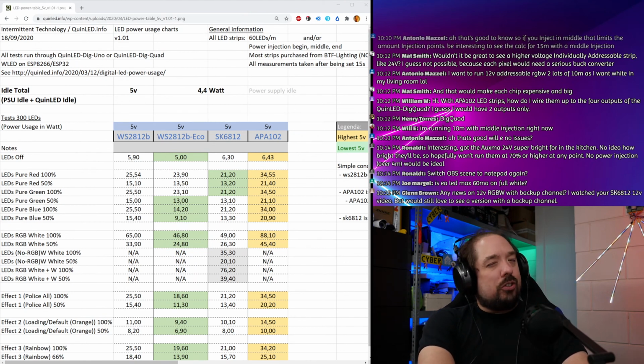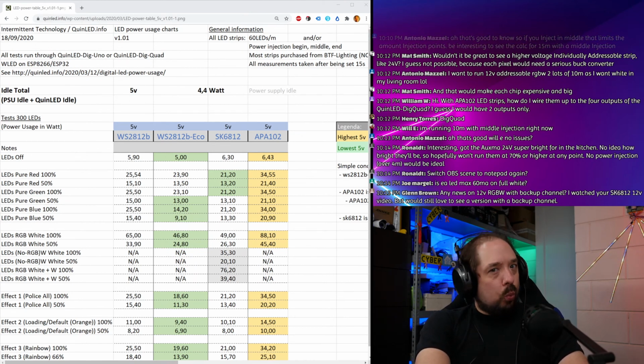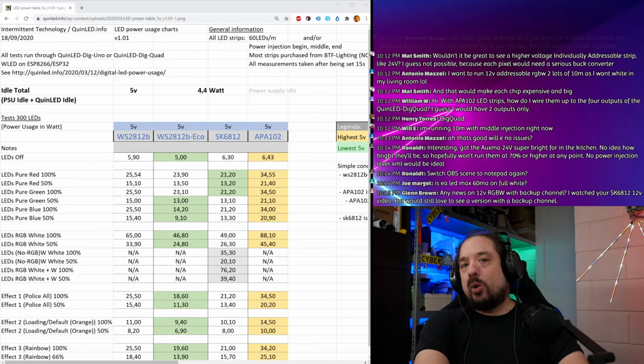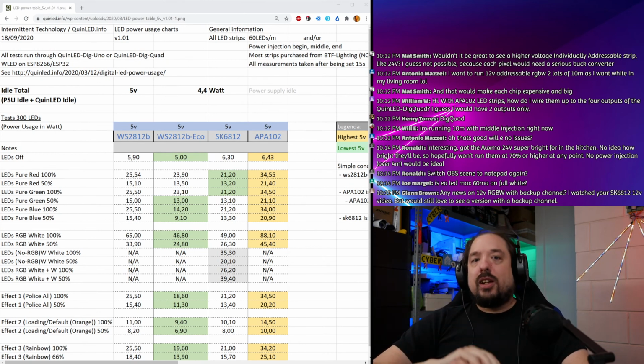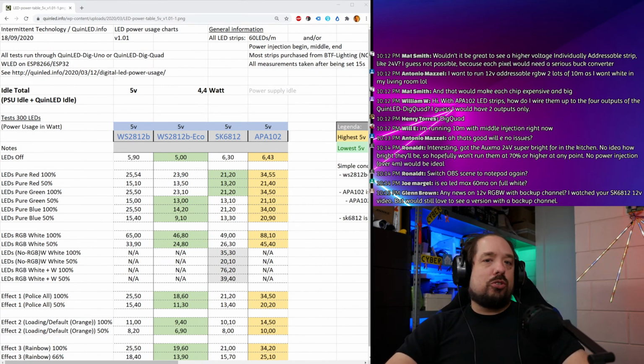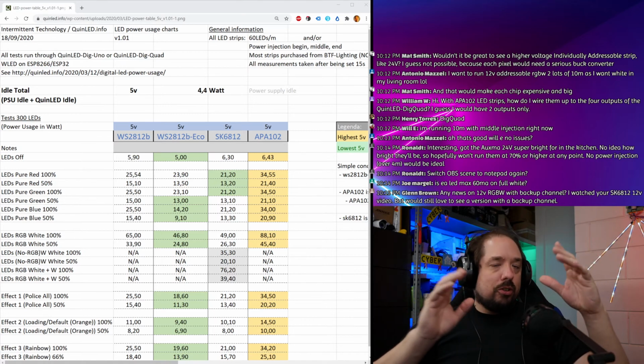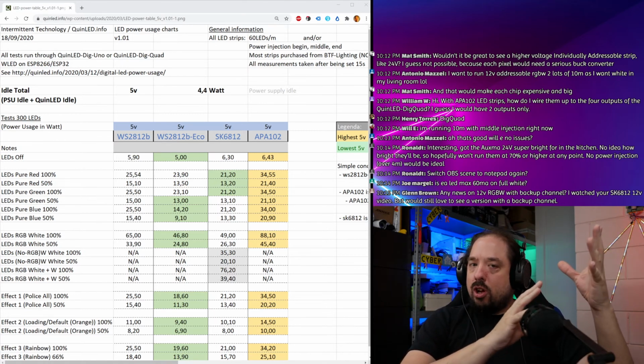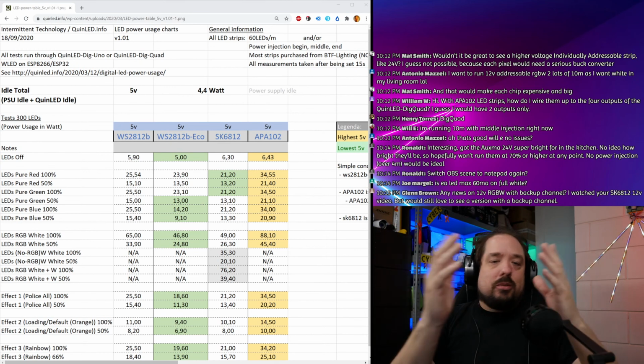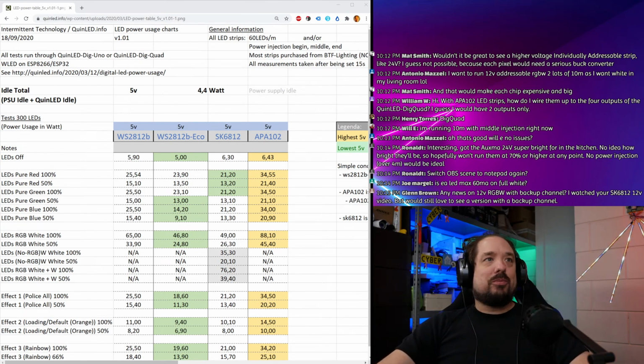And I also want to argue that you do not want to run RGB LEDs at white because they get really hot and white looks bad. So calculating with half is often a very good value, so you can do full power effects, full power single or dual colors often, just not white. But we don't want to run white.